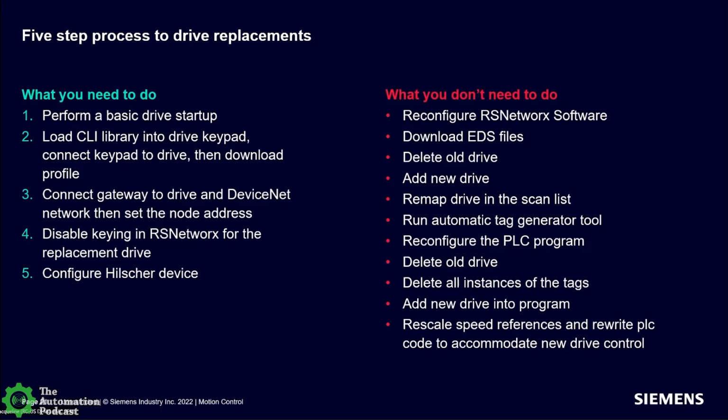So you would just perform a basic drive startup on the new SINAMICS drive. You would load the CLI library. Again, I'm throwing around this word CLI. It's essentially a configuration file for the SINAMICS drive, and it stands for command line interface.